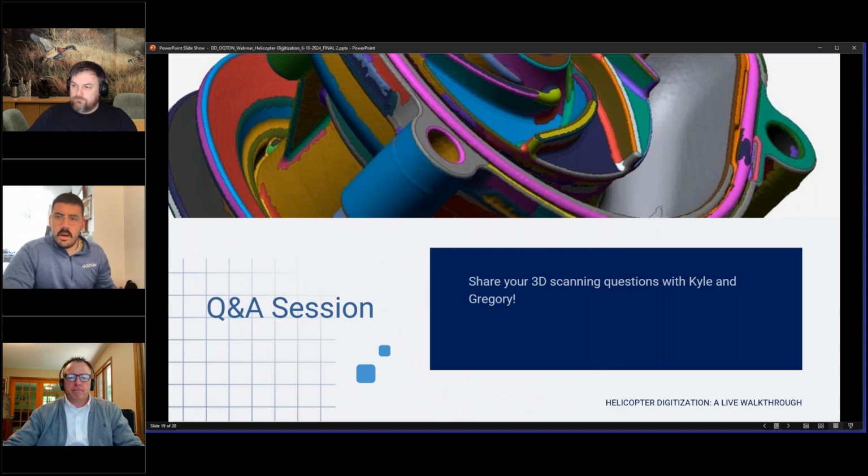Great, thank you. A question for you here, Greg. What is the best way to control the CAD dimensioning in Design X? How can you be sure about the dimensions? So when I hear people ask that question, I usually say that's the engineering part of the reverse engineering. When we capture these dimensions from devices like this, it's capturing the exact existing condition. So for example, if the bolt hole is a 3-inch hole, it's never exactly 3 inches. I mean, if your manufacturer is capable of doing that, we need to talk and figure out what they're doing. So it's like 2.98725, whatever, if it's really accurate.